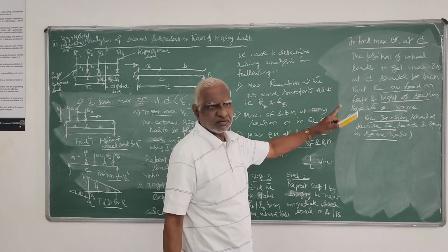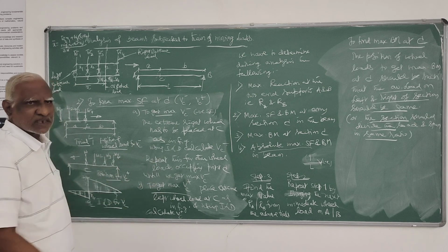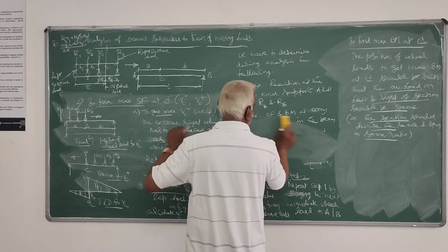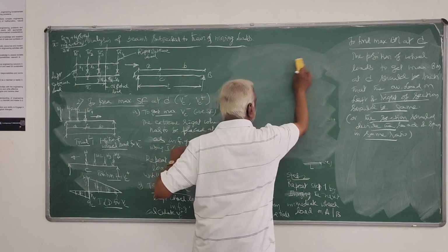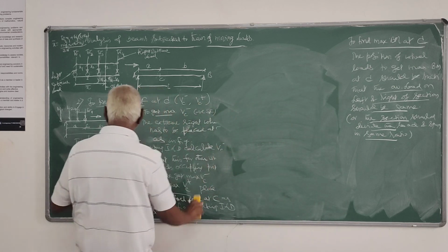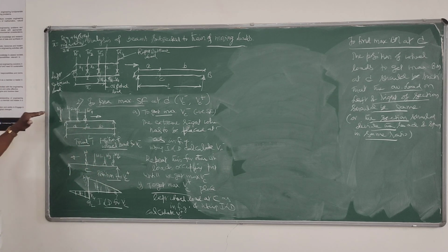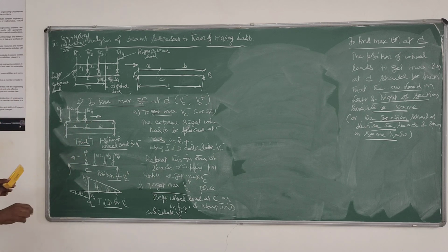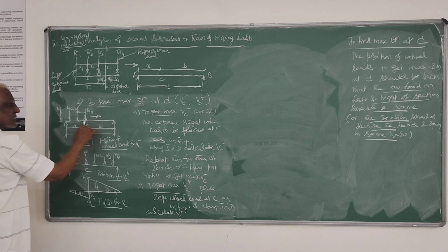So here, this is easier for computation. You have to do some preliminary exercise in order to arrive at that position of the wheel loads. So this is again a trial and error process. First, as you have seen in maximum shear force, allow the wheel load to move from left to right, and first place the extreme right wheel load at C. So when I place this extreme right wheel load at C, we assume this wheel load W4 is on the right side.